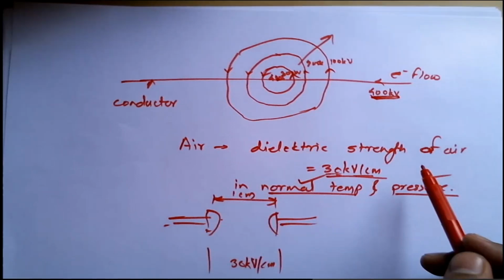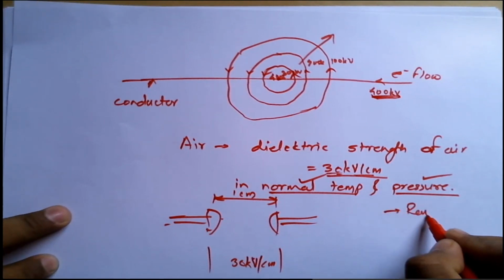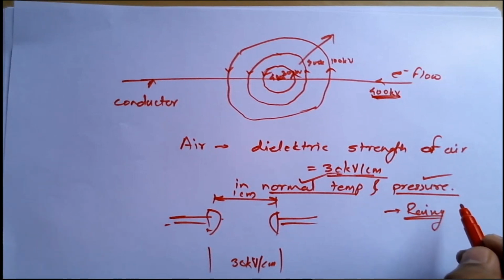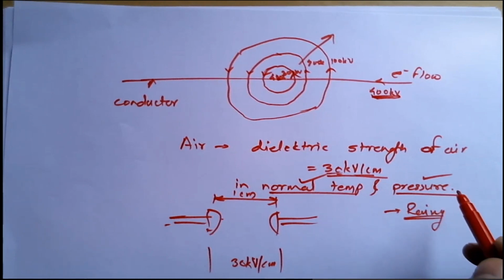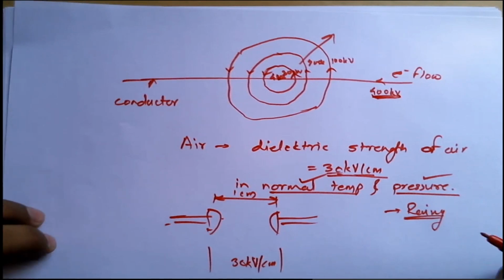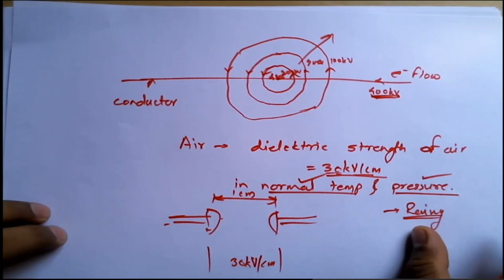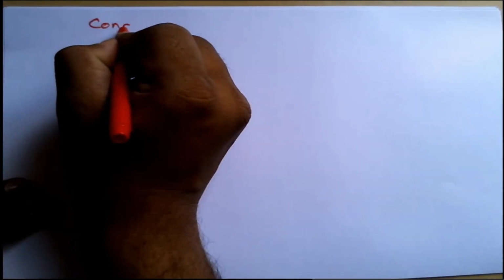Now, why is it happening, and is it always present near that conductor or only in specific conditions? It is present when there is a lot of humidity or moisture around that conductor in the air. In the rainy season, vapor or moisture in the air makes the air more conductive, and with less voltage corona occurs. So there are some conditions for corona to occur.